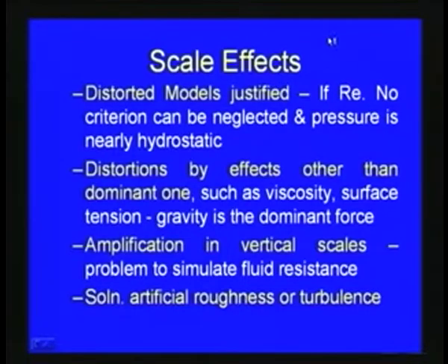When we use the distorted model, there will definitely be scale effects. So, we have to consider the scale effects. In many cases, as I mentioned, we cannot achieve all the geometrical similarities. That is why we go for the distorted model. Before going for a distorted model, we have to justify whether this kind of modeling, investing money and time and our efforts, is justifiable or not.